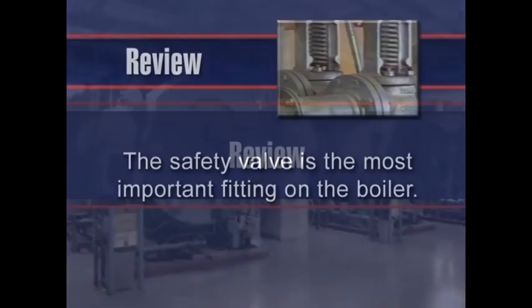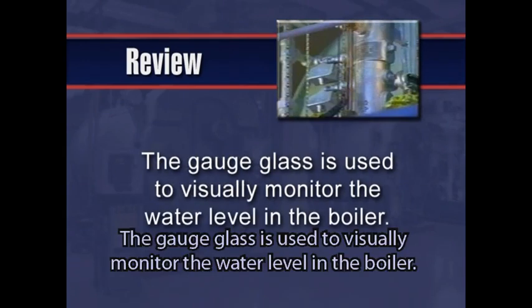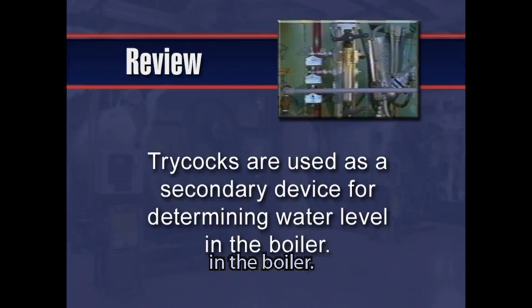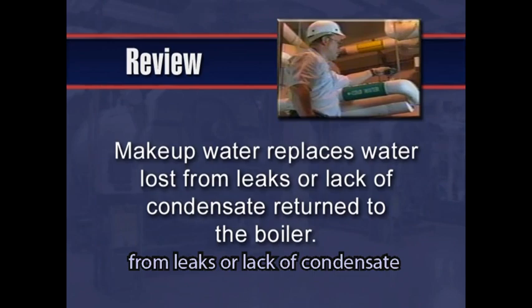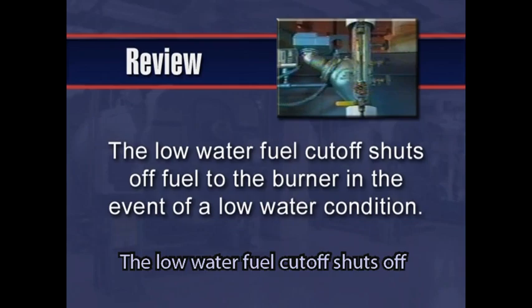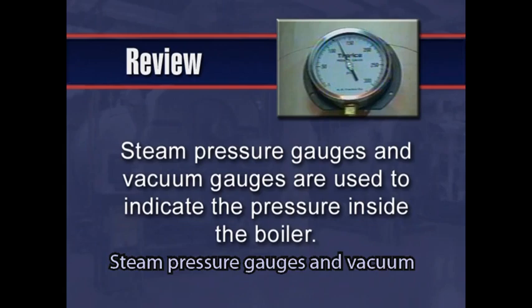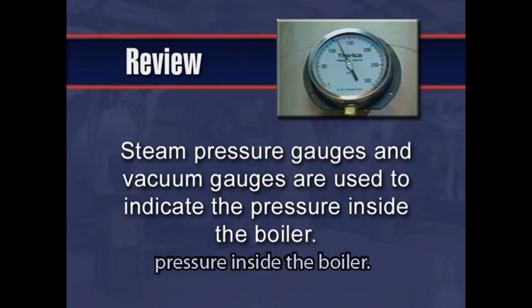Review. The safety valve is the most important fitting on the boiler. The gauge glass is used to visually monitor the water level in the boiler. Tricocks are used as a secondary device for determining water level in the boiler. Makeup water replaces water lost from leaks or lack of condensate returned to the boiler. The low water fuel cutoff shuts off fuel to the burner in the event of a low water condition. Steam pressure gauges and vacuum gauges are used to indicate the pressure inside the boiler.